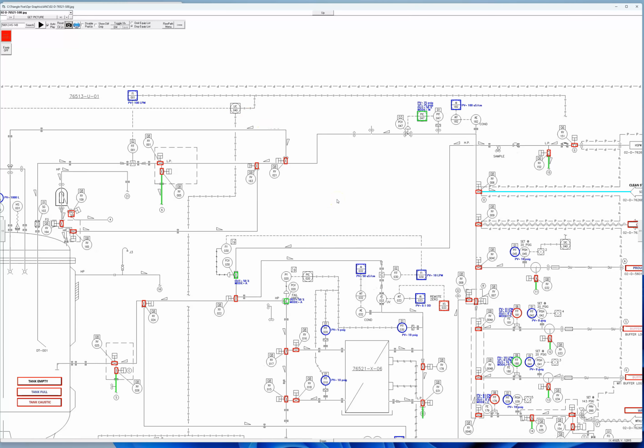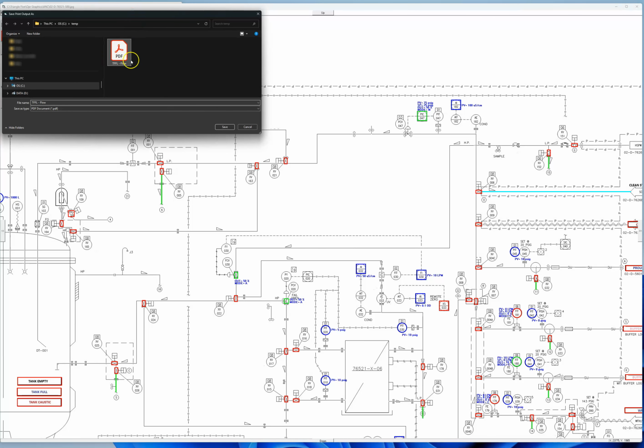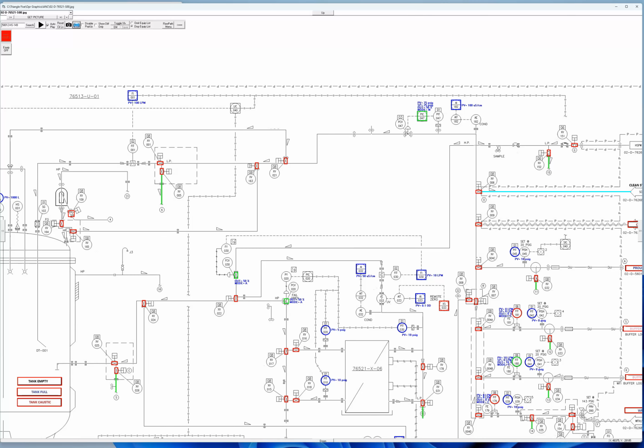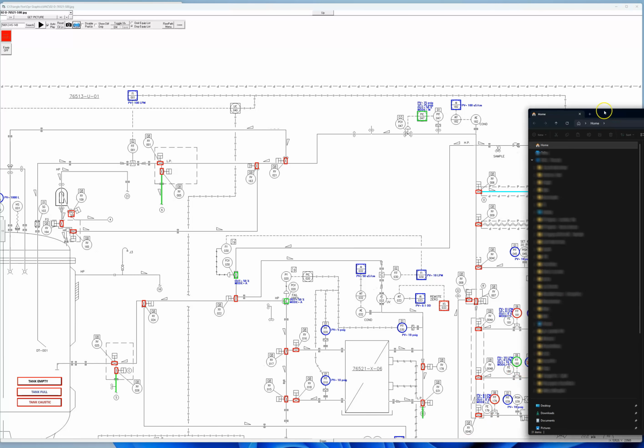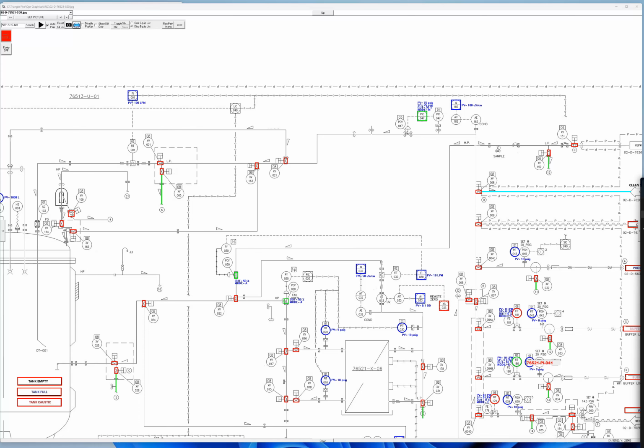This is a print, which basically prints to a PDF format. So within this tool, you have the ability to draw a series of flow paths, and that will show. I'll explain how that's done in a later video. Once you've got a series of flow paths or even one, you can hit this and it'll generate a PDF for you, which you can then distribute to various groups to look at. So let's do that. Let's name it TFF flow, save. Yes, so that one, I believe, is created here.